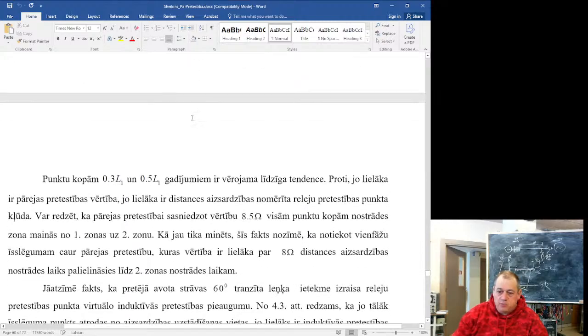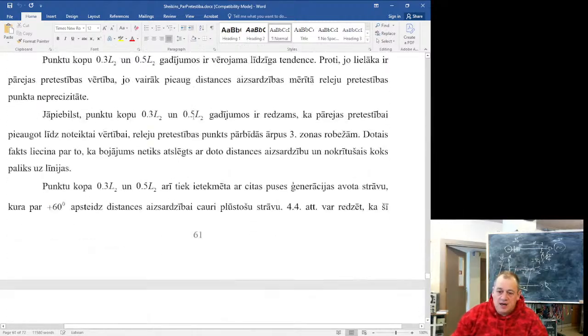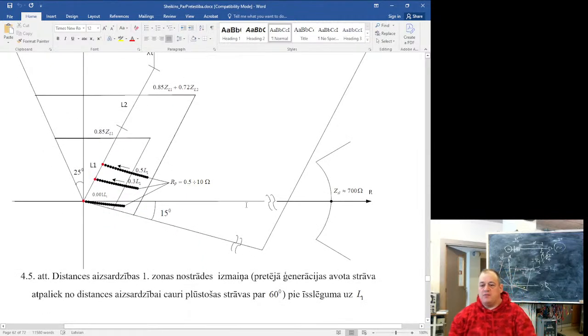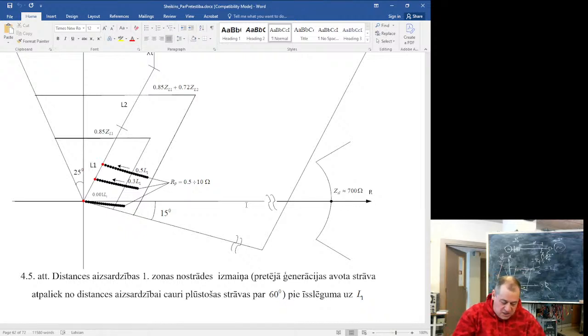Also, if you have a criterion of transfer from the opposite side, or a criterion of derivative of resistance, or resistance rate of change, in case of a burning tree, if you select this time interval too short, your protection will not operate because resistance changes slowly.